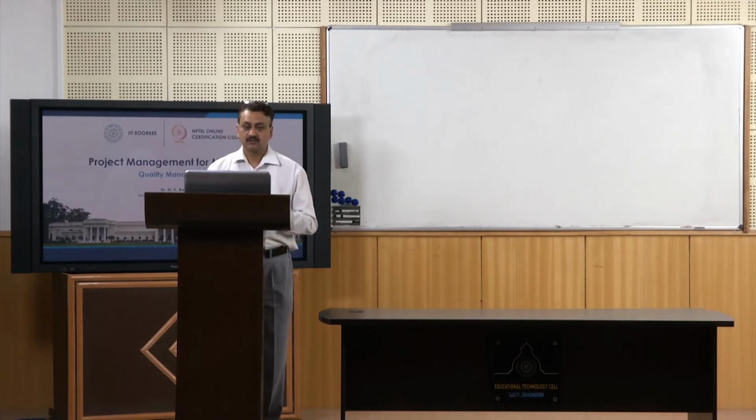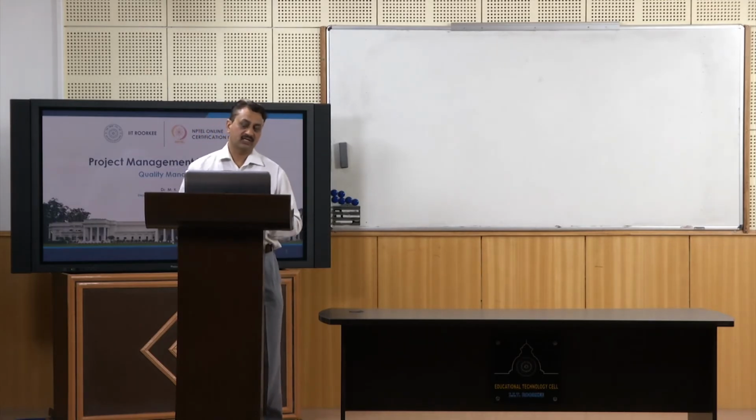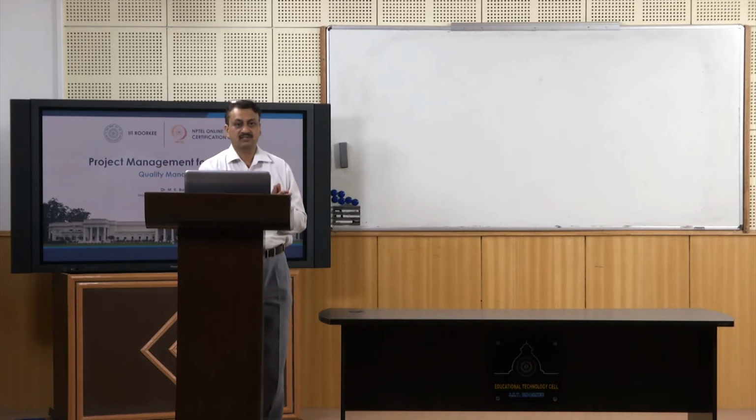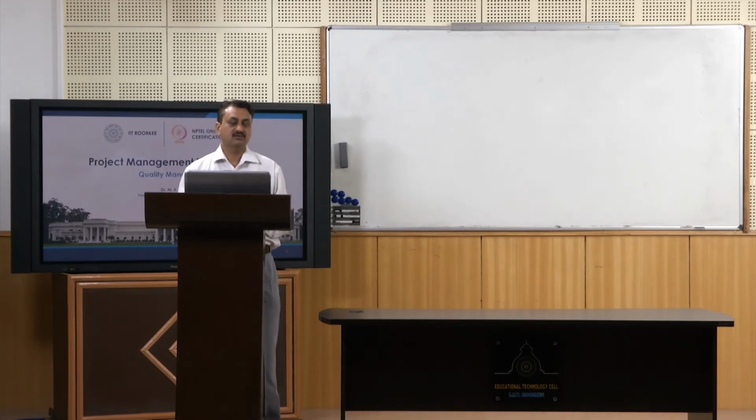So, if you look at this control chart and design of experiment, control chart, as I said, will tell you which particular product is faulty product, or at which particular time your machine is producing faulty product, and then you take corrective action using cause and effect diagram. But if you look at design of experiment, it is basically a proactive approach. Cause and effect diagram is reactive approach. So, fault has occurred and then you are analyzing causes. That should not be done actually, isn't it?